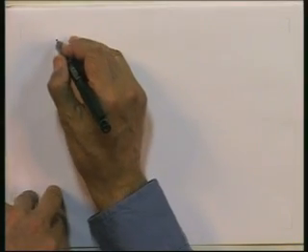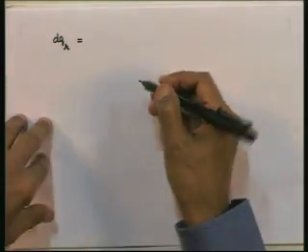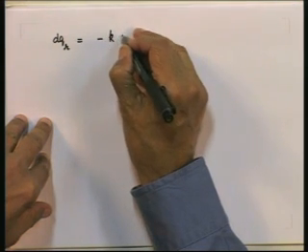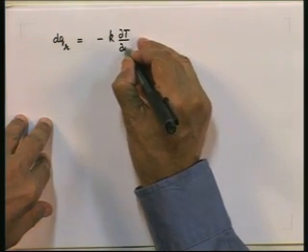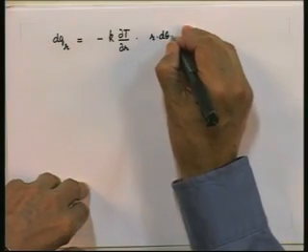All right. We want to put down expressions for each of these quantities. What will we get? We will get the following. dqr, the first one. Now, I am not going to explain again like last time, I will simply put down the expressions. dqr will be minus k dt dr multiplied by the area through which heat is flowing. The area through which heat is flowing will be r d theta into 1. We assume in the z direction that we have a unit width. So, that is the area.